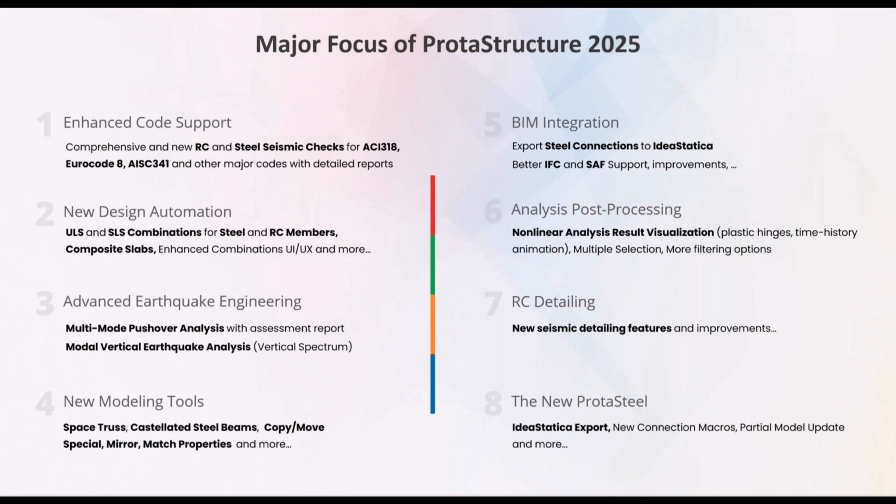And also in terms of earthquake engineering, we have developed multi-mode pushover analysis in this version, and especially for special structures with large span beams, large cantilever columns, or slanting columns, you can now calculate the vertical earthquake effect with the modal vertical earthquake analysis.